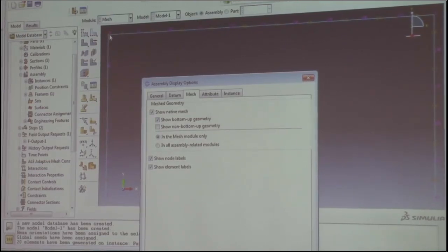Later we'll have the result of the bending moment along this beam, and ABAQUS will plot this bending moment along this node label. So it's from 2, and then you see here 9, 10, 11, so from 9 to 17. And the last node is 3. Because later when we plot this bending moment along this line, we need to give the information of this node label.